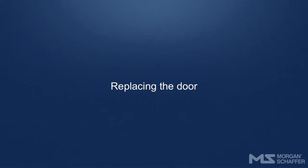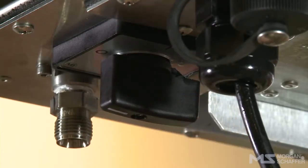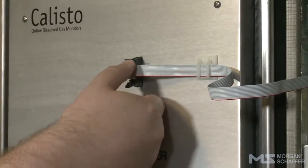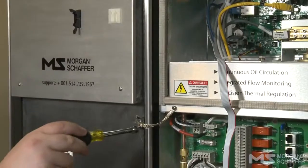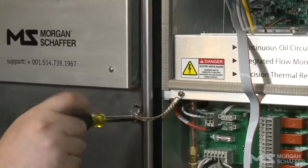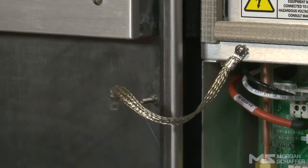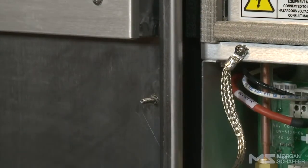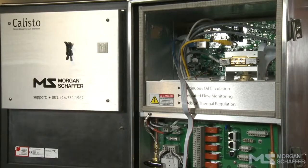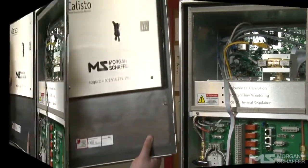Replacing the door. Turn off the Calisto and close its circuit breaker. Unplug the connector from the flat cable directly connected to the display. Using a 1/4-inch nut driver, loosen the screw while holding the ground cable connecting the door to the Calisto unit in place. Set the screw and the locking washer aside. Remove the defective door by pulling it upward.